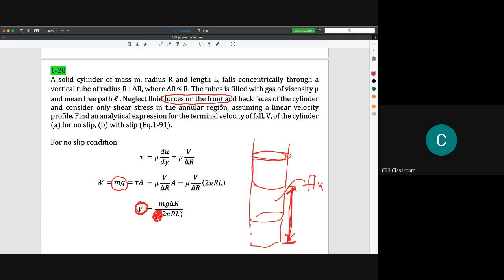And then if we want to add the fluid force here, as I said previously, we could have the value of CD, the drag coefficient for a cylinder, by looking at tables or the handbook. Okay, and then we add in shear stress, sorry. So the idea is now you have the weight here, and then it will give you a drag force in the reverse direction and also the shear force in the reverse direction.